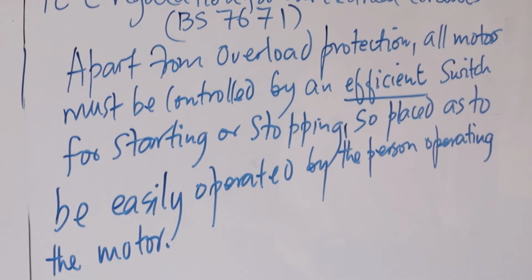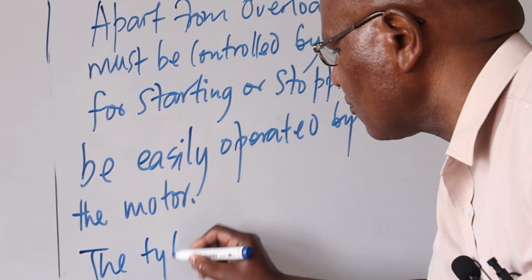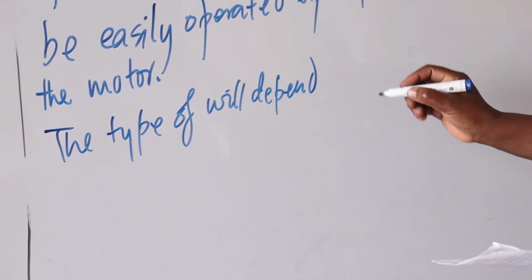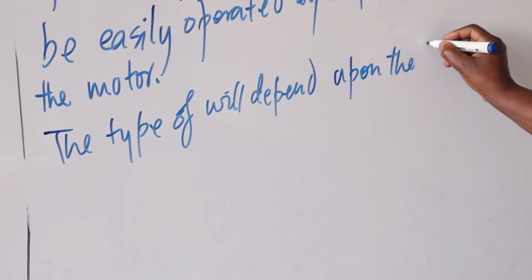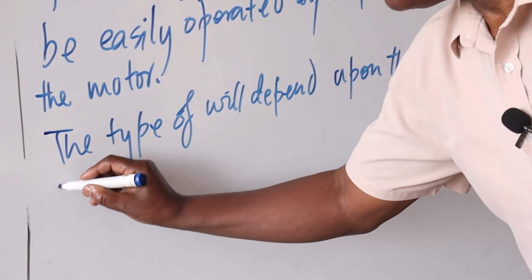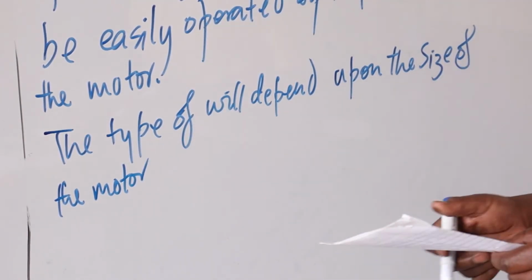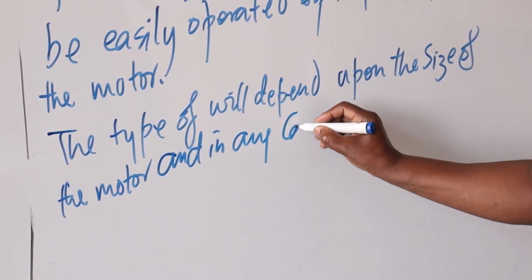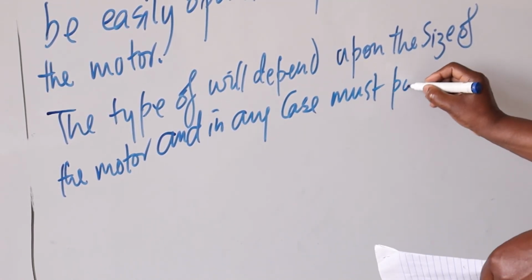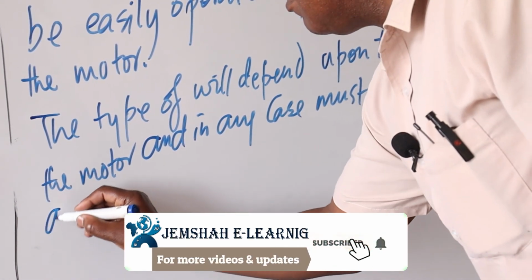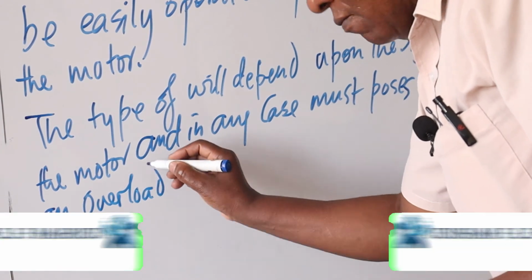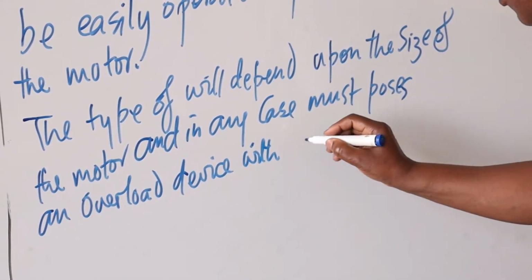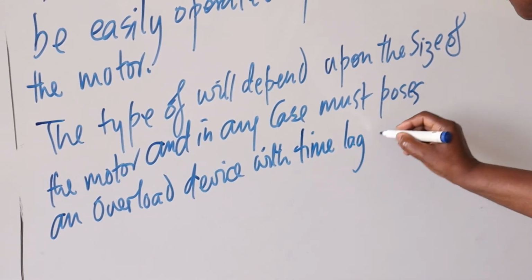Now, for this, we use starters, and the type of starter will depend upon the size of the motor, and in any case must possess an overload device with time lag characteristics.